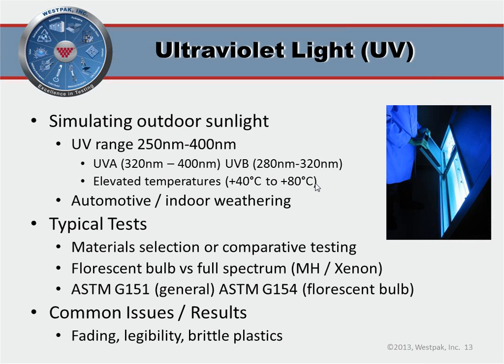And the other thing, people think UV, they think outdoor weathering. Well, you should also consider if your product might be subjected to indoor weathering. If it's an automotive product, if it's inside the car, the window filters some UV light, but not all. And then also indoors, if something's near a retail storefront or near someone's window, it will weather. I'm sure everyone's had something at home sit by the window and it fades and weathers over time.